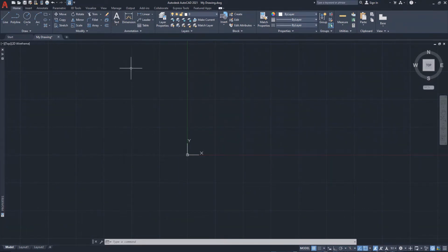Back in our first video, in a review of the AutoCAD user interface, we briefly visited the location down in the Drawing Aids toolbar where the user accesses changing the current annotation scale setting. We see that the current setting is at 1:1. This tells us that any annotative object created from this point forward will be assigned an annotative scale of 1 to 1.